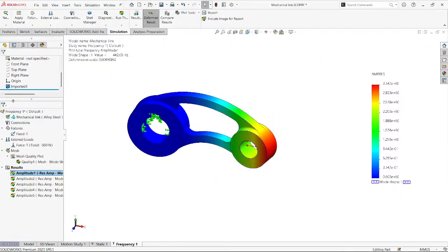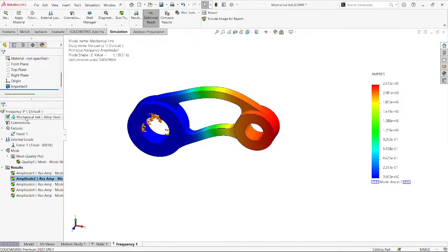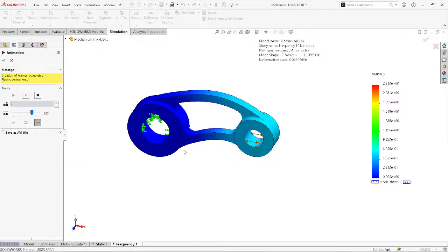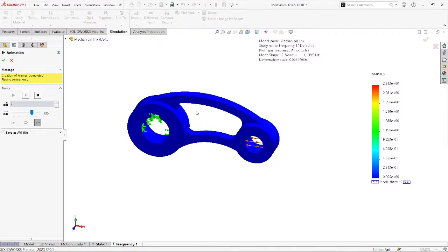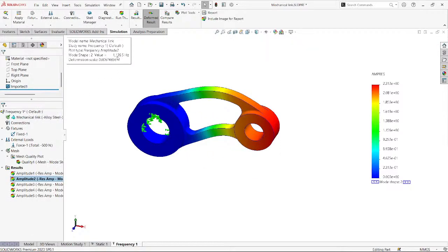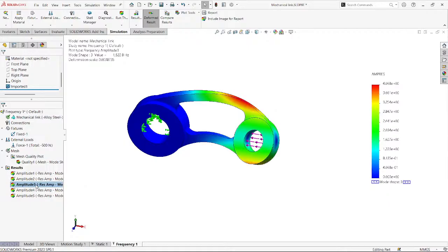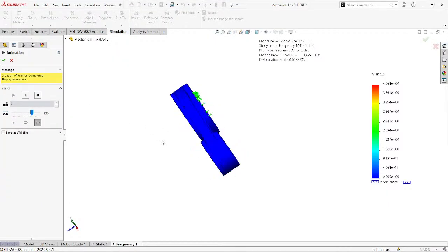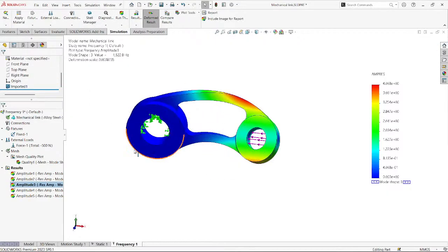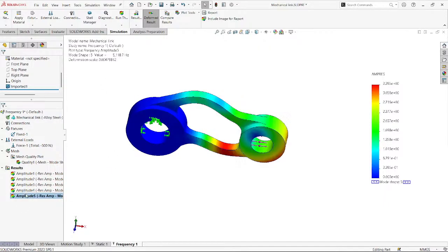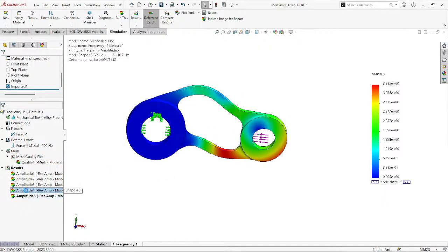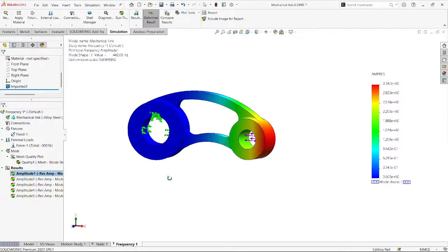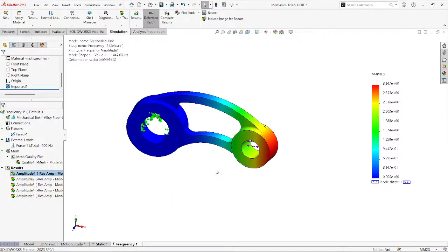Okay, and then if I see this load case and animate this, it is trying to buckle here. This is also not critical for me. It is 1113. It is not going to happen. This is also not possible because again it is deflecting some other regions. My load case is exactly straight, so it is 1600 hertz. I don't think I'm going to have this kind of scenario. In short, you could see as per the rule, the first mode is perfect.